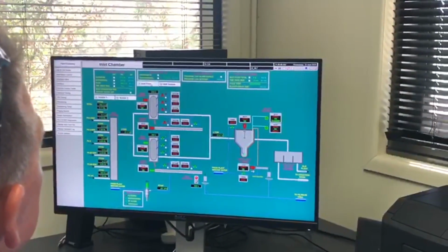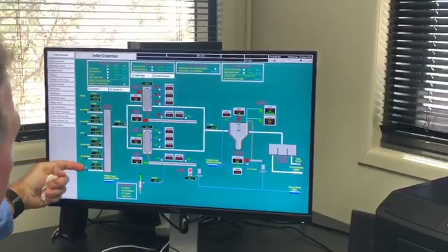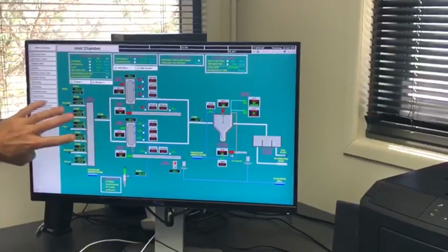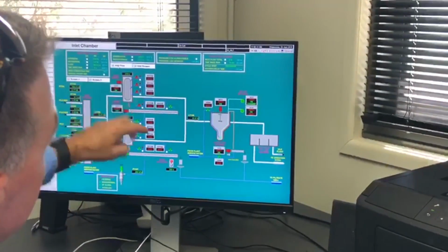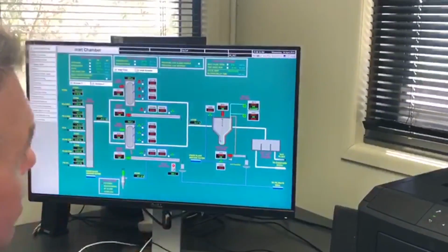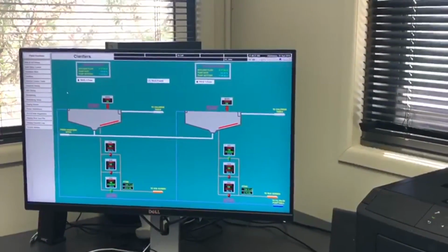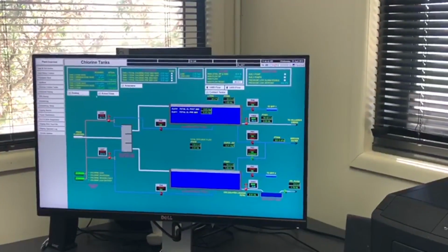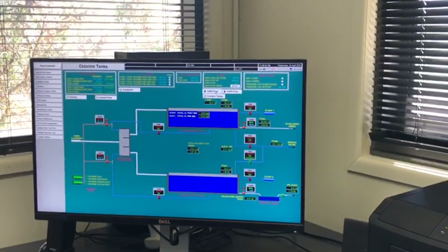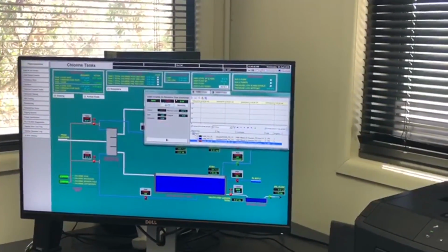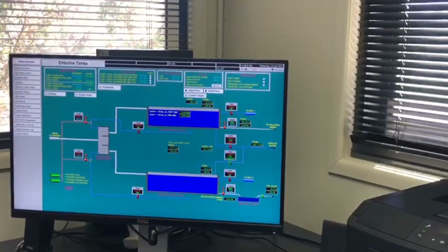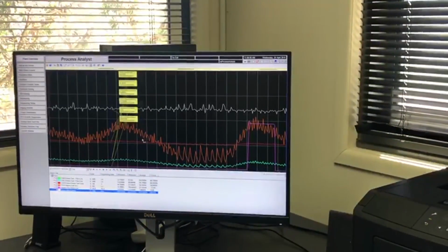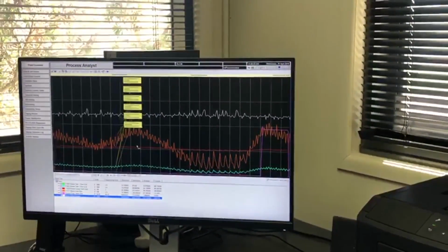About the monitoring and control system, there is a Siemens SCADA automated control system installed. It is a standalone system where the plant is not networked with other stations in the same region. The system monitors and controls every single stage of the plant by reading sensor information and running pumps, valves, batchers, machines, and generators. Several sensors are placed at many points of the plant to provide useful information such as chlorine concentration, effluent flow, pump and machine status, percentage of dissolved oxygen, and others.